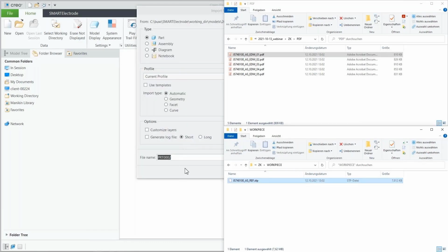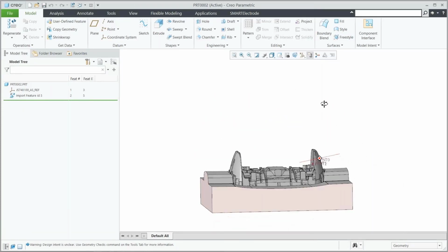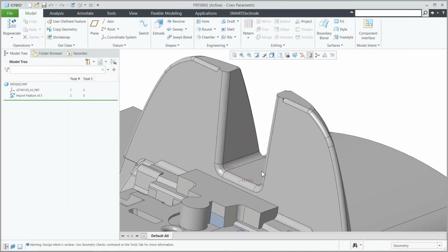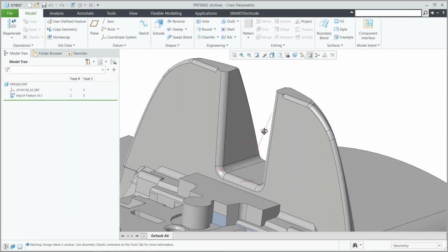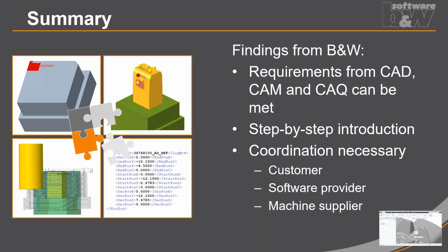And now also we're going to import the workpiece step file. And you can see also the measuring points are added as datum points to the step file and can be imported again. So this should normally be possible to read the data in your software at the CMM.